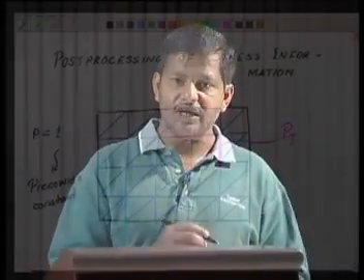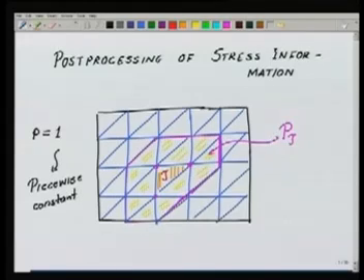Okay, so just like we did in the one-dimensional case, for the bar problem and the beam problem, we can do the same thing here to set up the system of equations in terms of the coefficients Ai tau, Bi tau and Ci tau, solve, and get the representation of the recovered state of stress in the element tau. This way I keep on moving from one element to the next element. If I am interested in this element tau, I take the one layer neighborhood of that element tau. If I am interested in the next element, I take the one layer neighborhood of that element. So this can be nicely written in an algorithmic way.